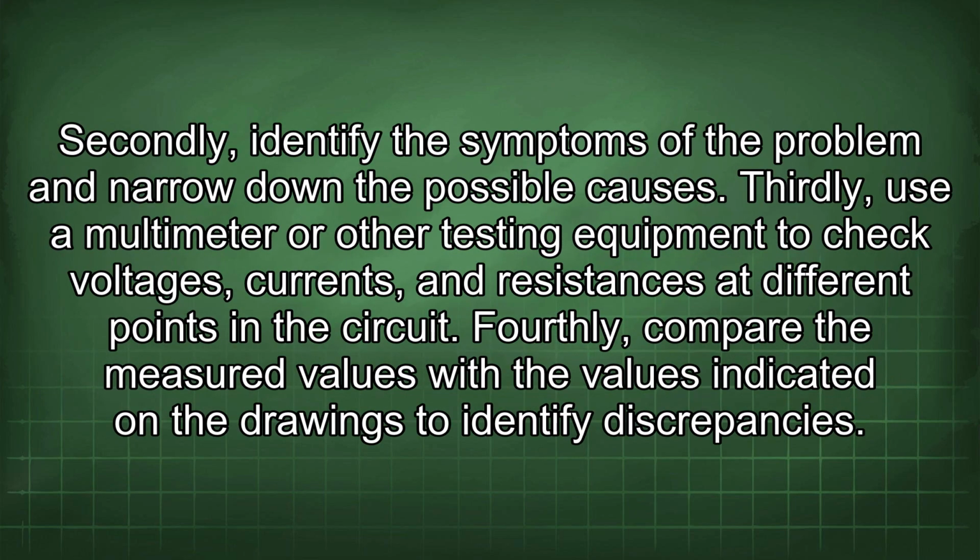Secondly, identify the symptoms of the problem and narrow down the possible causes. Thirdly, use a multimeter or other testing equipment to check voltages, currents, and resistances at different points in the circuit. Fourthly, compare the measured values with the values indicated in the drawings to identify discrepancies.